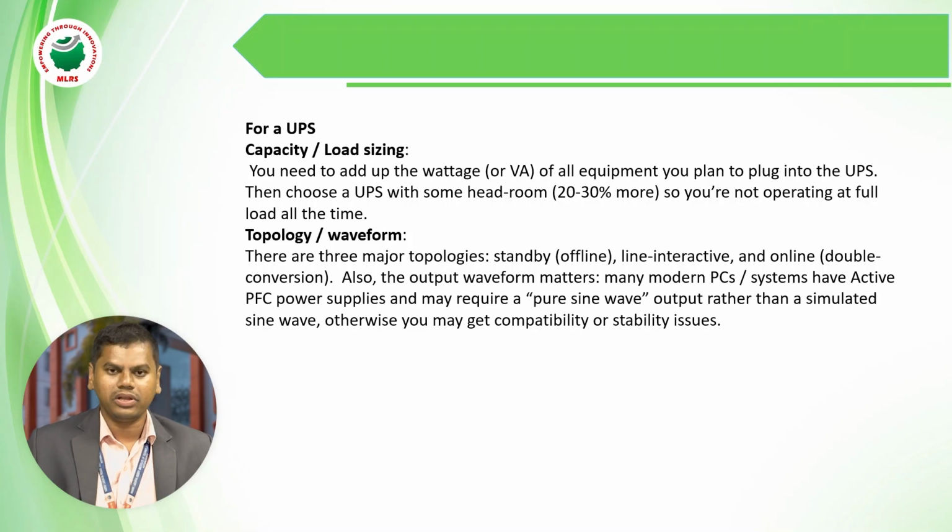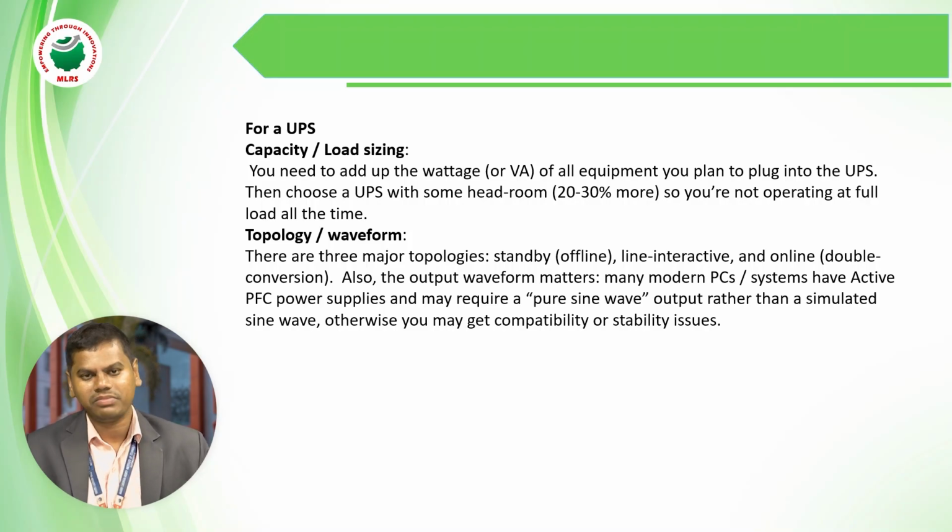Next, topology, which is about the UPS waveform. The purely ideal waveform is the sinusoidal waveform. There are three major topologies. One is standby, which is the offline UPS. Next, line interactive, and next, online. Online is nothing but double conversion.